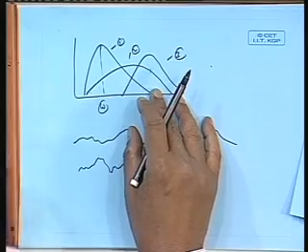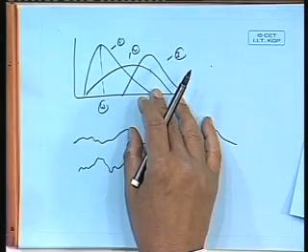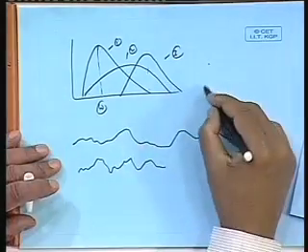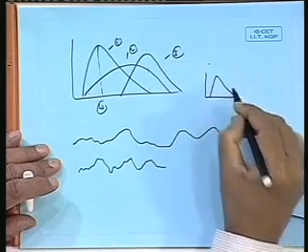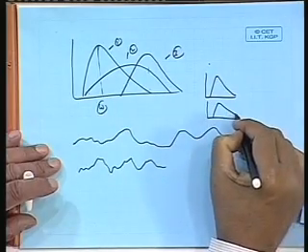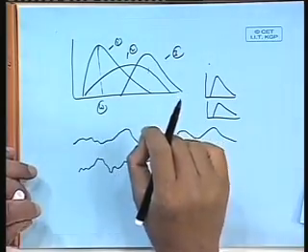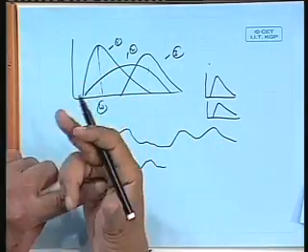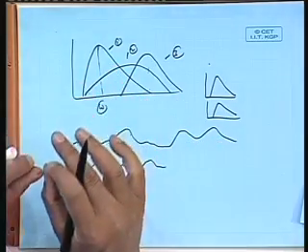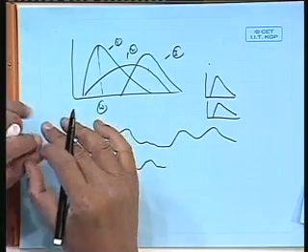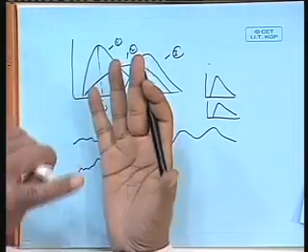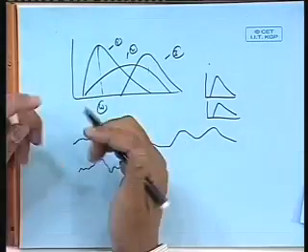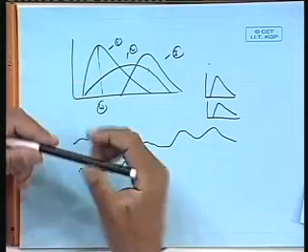Now the question is, if in the Bay of Bengal in the month of July I measured today and got a spectrum like that, should tomorrow also become like that? The answer is, just think, what parameters might cause the waves to be excited. Number one, wind speed, that is for sure. Number two is obviously the local bathymetry.